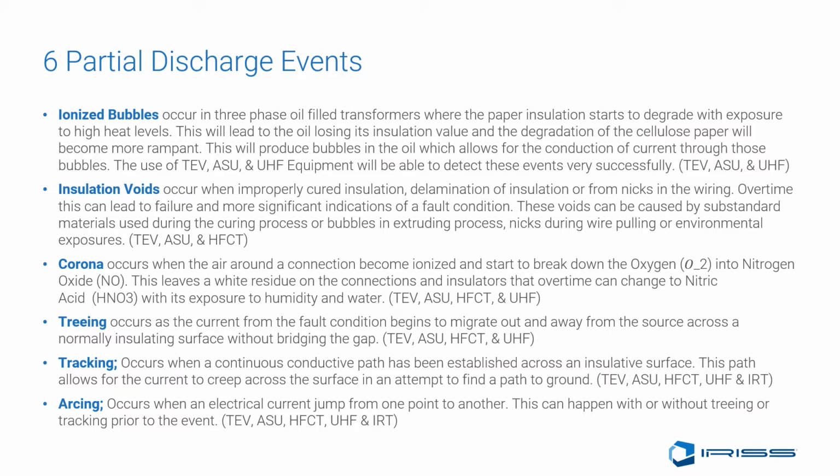Sound analysis can also be a key determining cause of the exact fault condition that's present when looking for these 6 partial discharge events. They will each have a distinct pattern when viewed in software, and in a time signal analysis versus the frequency spectrum. These distinct images, in conjunction with the PRPD screens and level modes, allow the inspector the ability to make a decision about what steps to take next in the asset's health.